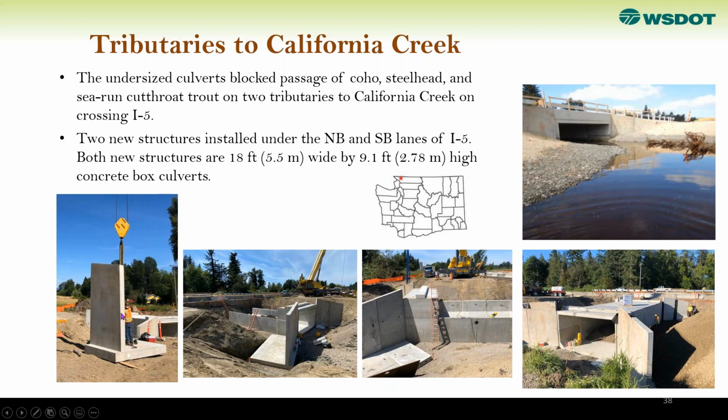Okay. Next question is, it appears that you're increasing flow areas to reduce velocities and improve fish passage. Won't these improvements increase floods downstream? Maybe Michael or Mark, do you want to cover that? I think I can probably take that one. So when we design one of these crossings, we look at those kinds of factors. But in general, you can increase the channel that the water travels through, but that doesn't really affect the amount of volume that travels through there during flood events. And floodplain design is part of the consideration.